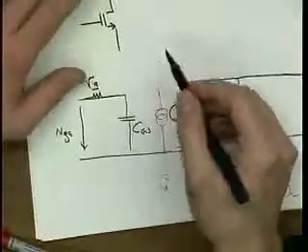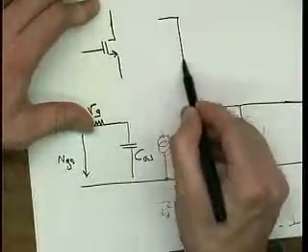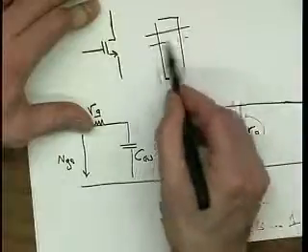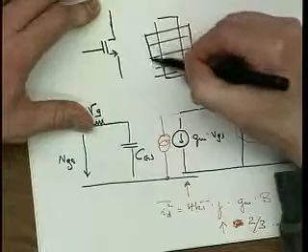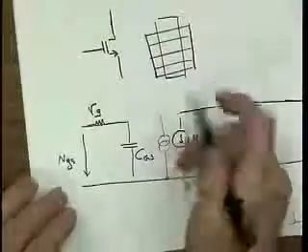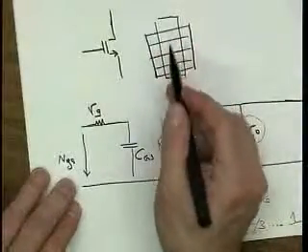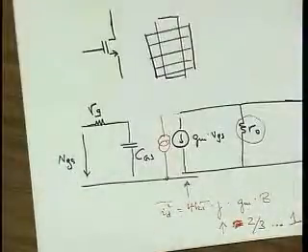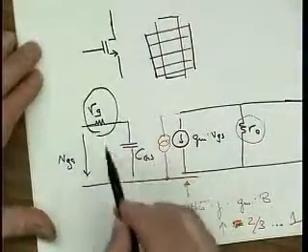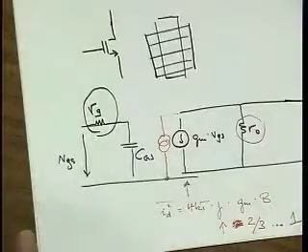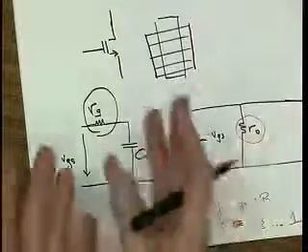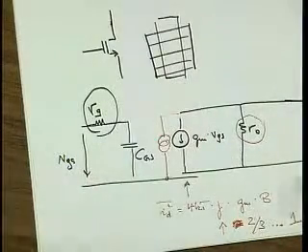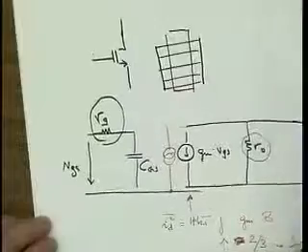So in those cases, you actually find transistors that are laid out, again, as fingers, lots of fingers. Very short, stubby gates. They are tied together on both sides, strapped with metal, and so the effective resistance of the gate is minimized. So you've got to be careful about stuff like this. Probably not for most of what we're doing in this course, but if you do the right or wrong thing with the transistor, it may matter. Right, and there are a bunch of other things that sometimes do matter.